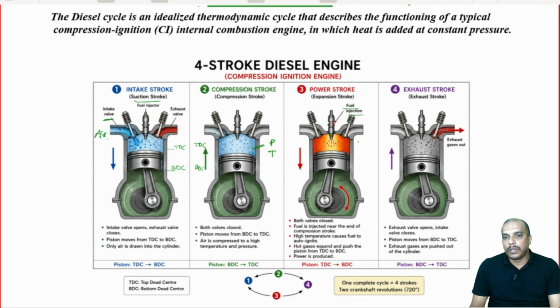All right. Now, the moment the auto ignition happens, the piston starts moving from top dead center towards the bottom dead center, and for some portion of this total swept volume we are still supplying the fuel. This is very important in a diesel engine.